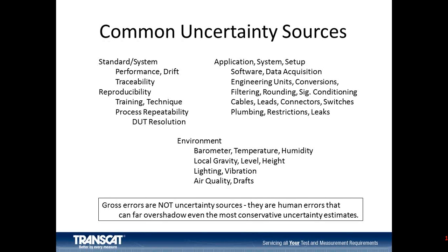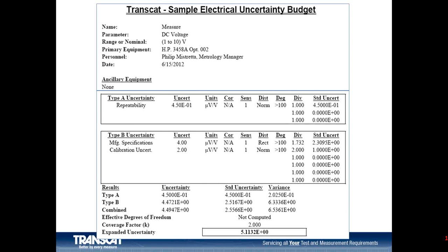All right, so here's an example of an uncertainty budget, as we call it. This is a screenshot from a spreadsheet, such as Microsoft Excel, a nice tool for tabulating these different influences. And this is called an uncertainty budget because it is an allowance for various different parameters, so that we don't have to make this uncertainty calculation every time we make a measurement.